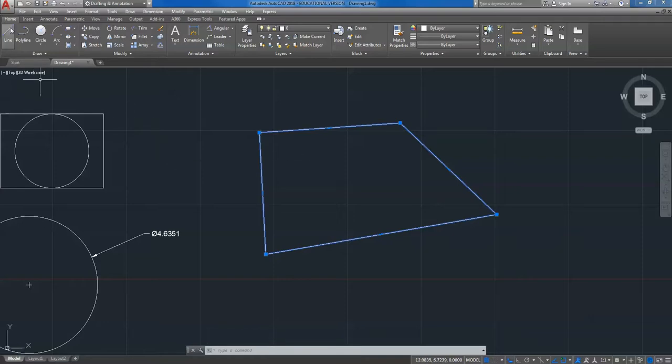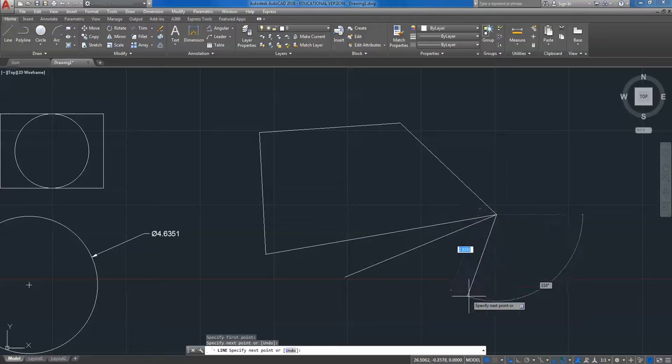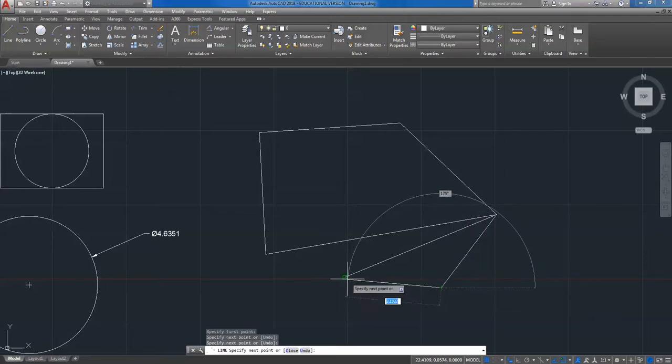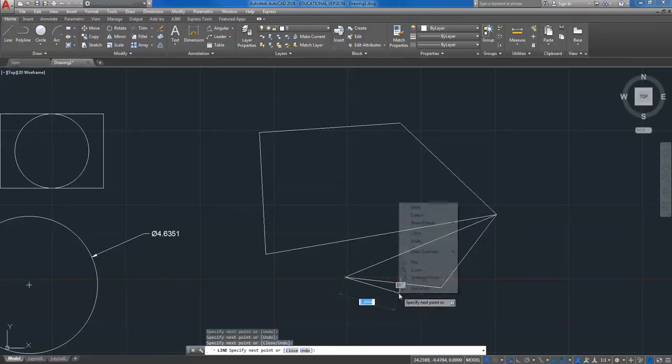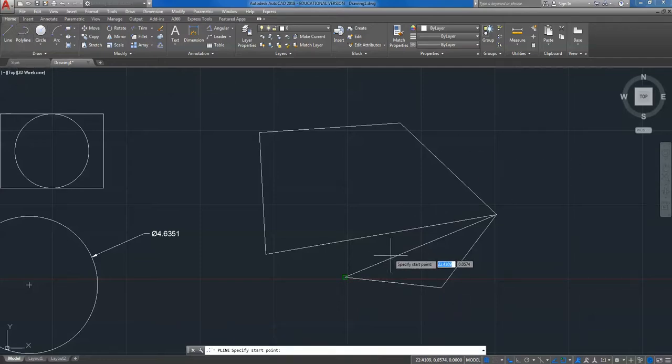And the text will ask you to create a polyline that is a particular length, thickness, okay? Oh, I'm sorry. I just clicked on line. I should have clicked on polyline. So what you'll notice is specify next point or arc, half width, length, undo, or width. The textbook asks you to do a 0.03 width.